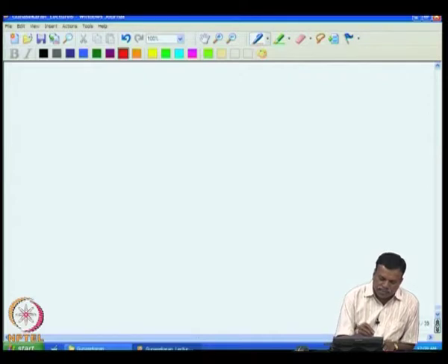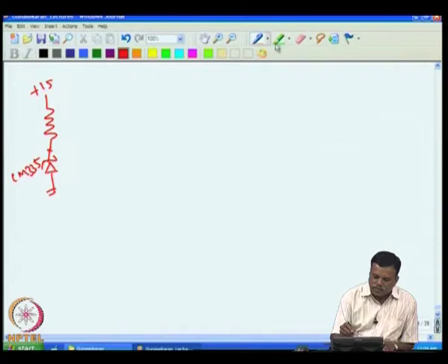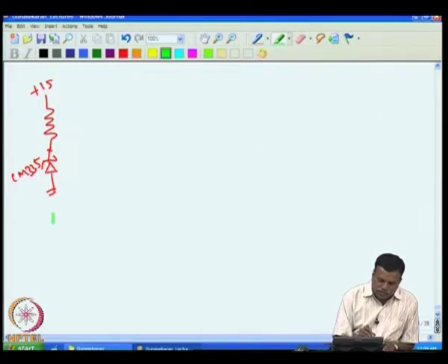The PI controller looks like this. So, you have, say, a temperature sensor. This is similar to what we had here. For example, I can have an LM335 as a temperature sensor. Then I can also have a reference voltage.